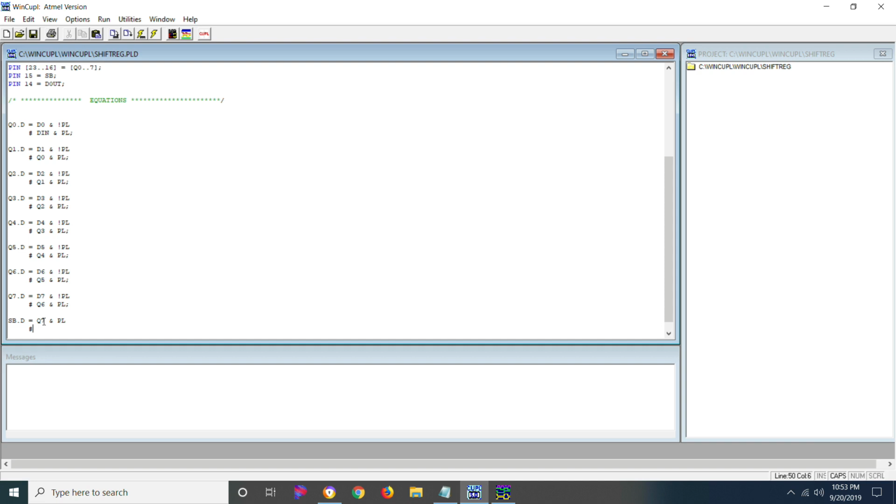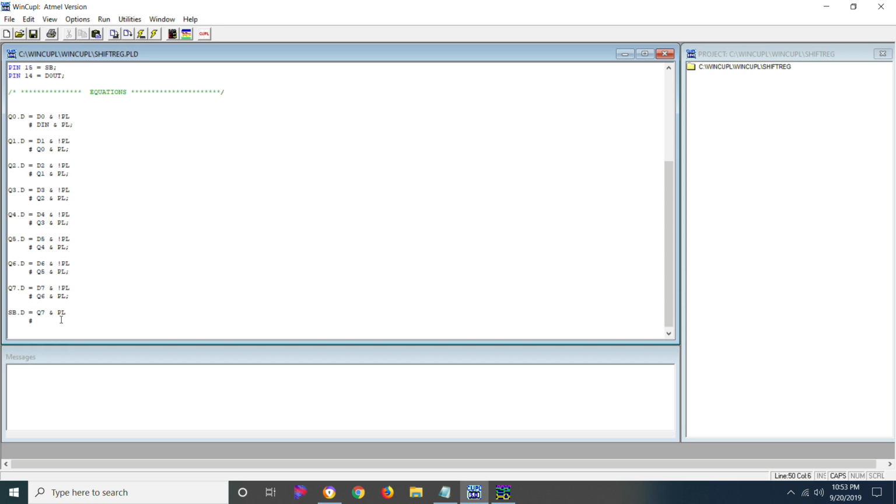Well, one thing to think about is if the initial state that it needs to be in is high, then the only thing that we would be concerned about is its initial state. Well, what happens when we try to load data into the registers? Well, obviously we have to bring parallel load low. So the OR on this would be if parallel load is low, then it needs to go high. So that's going to be our logic for our start bit.